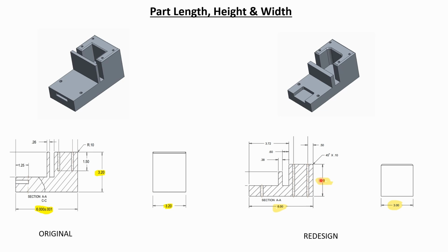So the stock sizes will normally come in a whole number, maybe like 3, 2, 4, and sometimes they go to half sizes, or they might even go to like 3.25. But always check before you design. Before you come up with a hard number, check and always design to the values that require minimal work to achieve. Because remember, that waste is being paid for by somebody. The waste is not free. It's not going away for free. That waste has been paid for. So you minimize that.